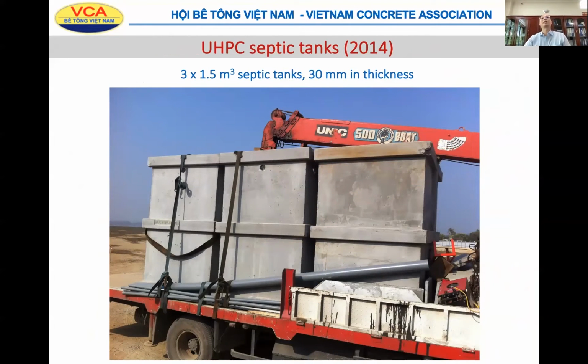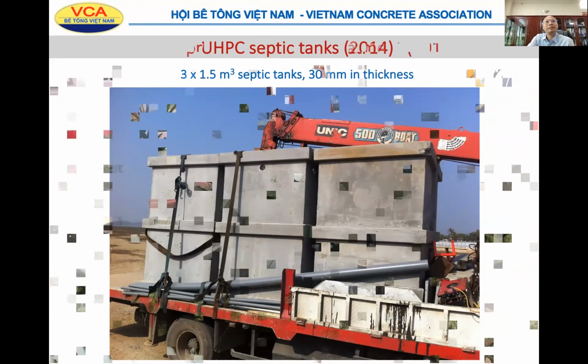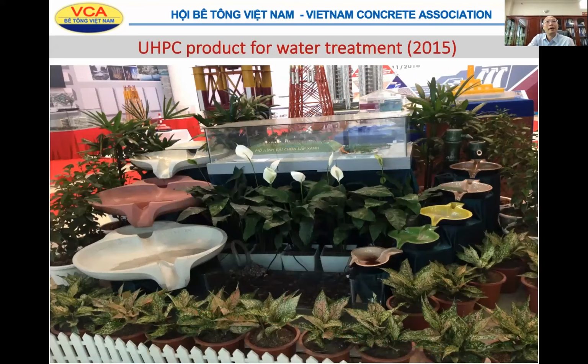Another application, we use UHPC for septic tanks, and the septic tank is quite light and quite thin, just 30 millimeters in thickness. And another research group tried to use UHPC for water treatment. It's quite colorful, isn't it?